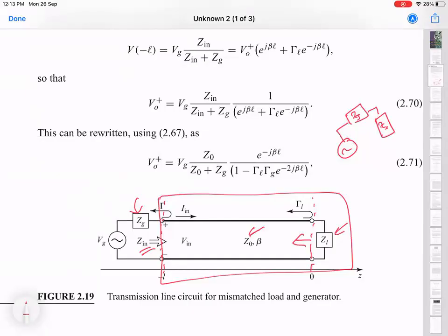So whenever you have a section of transmission line whose characteristic impedance is the same as the source impedance, then in some sense nothing actually happens. Okay, so let me expand on this. You can, for all practical purposes, just ignore the transmission line which is present here, because its only job is to take the signal at this point and reproduce it at this end.